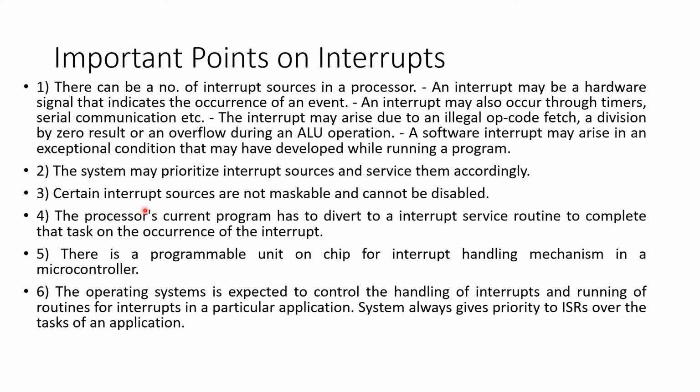Certain interrupts are very important: they are not maskable, they cannot be disabled. A system always has to give importance to the interrupt service routine to complete that particular task, and there is a programmable unit on chip for handling the interrupt mechanisms in a microcontroller.